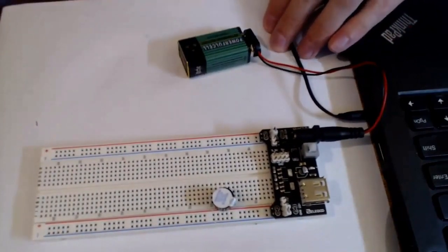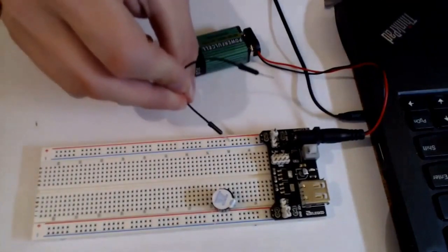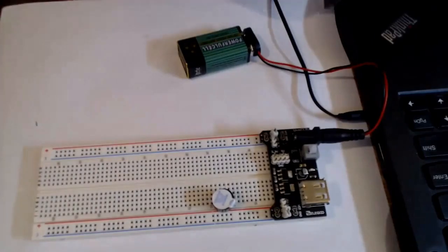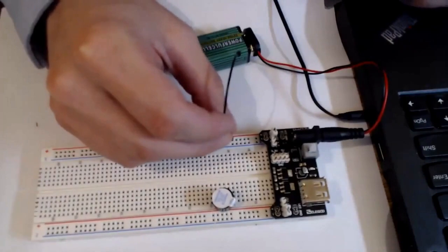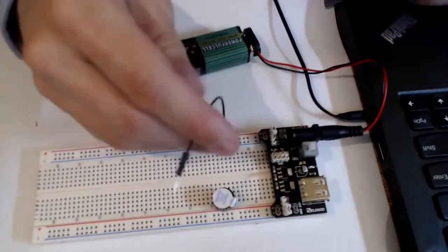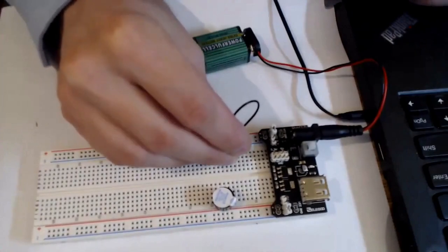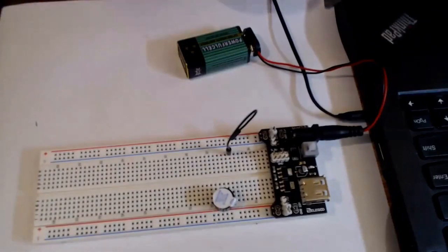Then the next thing that we're going to do is create the circuit to flow from this positive rail around the buzzer to the ground. So we'll start with taking this positive and going to row 20 to give it power. This is now A20. And I've got these listed out in the PowerPoint as well.